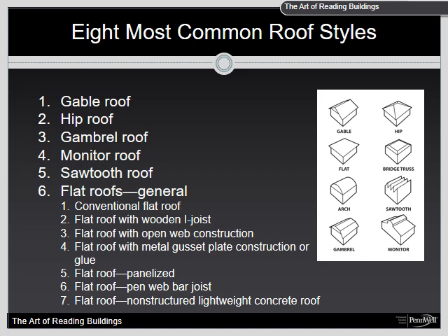Hip roofs next. The hip roof is similar to the gable roof, but the flat sides of the A-frame are replaced with a sloped roof. The hip roof appears more like an irregular pyramid. Similar to the gable, conventional hip roofs consist of a ridgepole, and then hip rafters are installed from the ridgepole down to and across the corners of the outside wall.